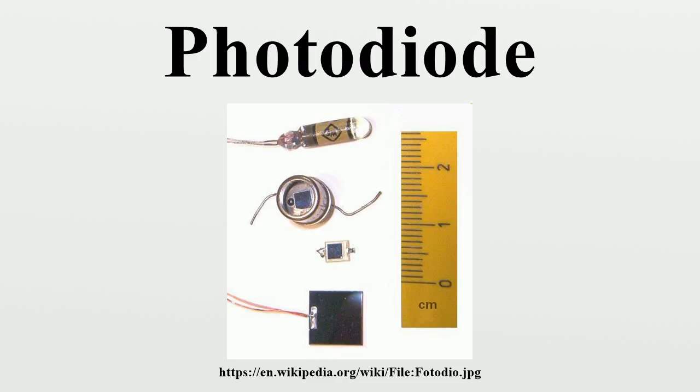The total current through the photodiode is the sum of the dark current and the photocurrent. So the dark current must be minimized to maximize the sensitivity of the device. Photovoltaic mode. When used in zero bias or photovoltaic mode, the flow of photocurrent out of the device is restricted and a voltage builds up. This mode exploits the photovoltaic effect, which is the basis for solar cells. A traditional solar cell is just a large-area photodiode.